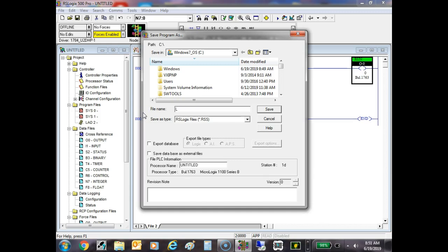So all that's telling us, guys, is that the syntax is correct. It doesn't mean the circuit is correct. It means the syntax is correct. So if you use O's instead of zeros, or vice versa, you'll never be able to clear that error. And it would pop up down there saying that you got an invalid address. And so on that run.